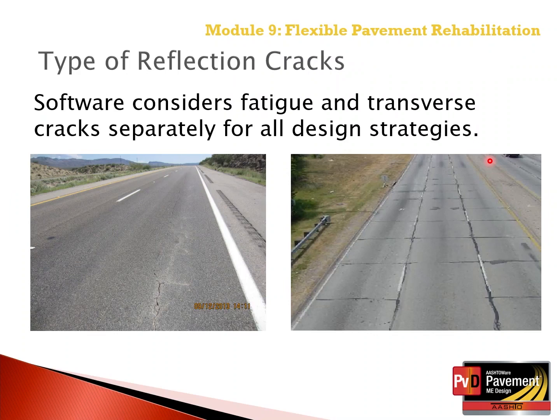The information presented and explained in this session is the same as discussed in Module 6-2 on semi-rigid pavements related to the reflection of transverse shrinkage cracks and fatigue cracks in the chemically stabilized base layer through the asphalt layers. In addition, Module 8 also included the same information on reflection cracking of asphalt overlays of jointed plain concrete pavements, fractured jointed plain concrete pavements, and continuously reinforced concrete pavements.